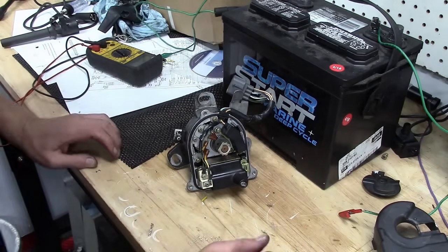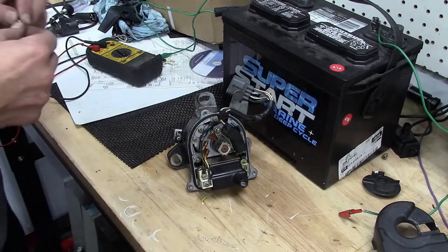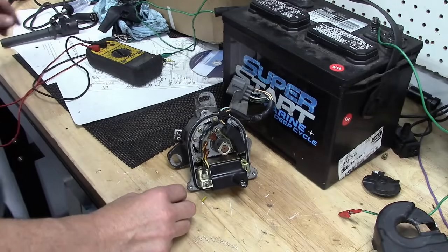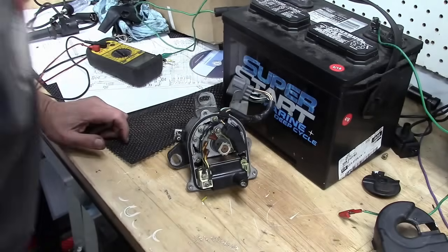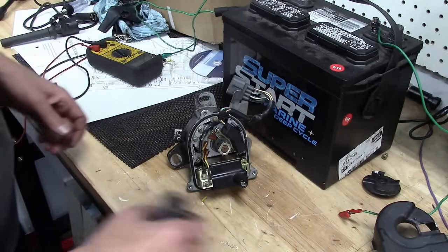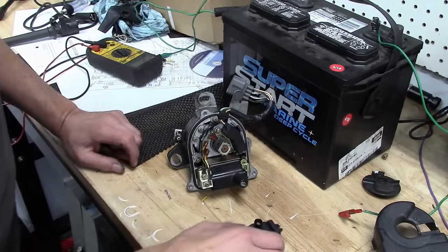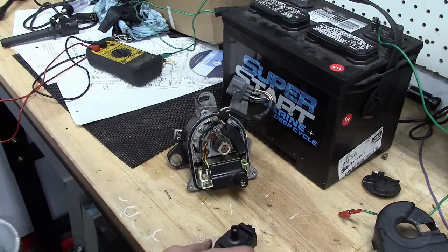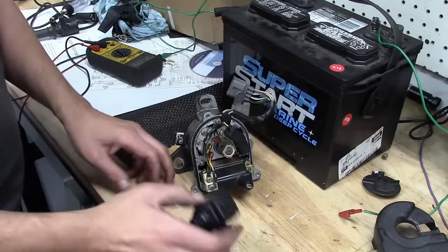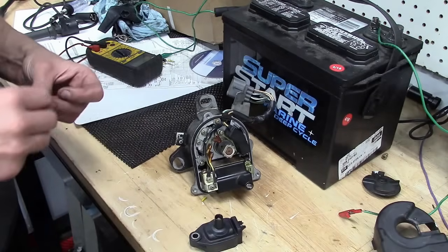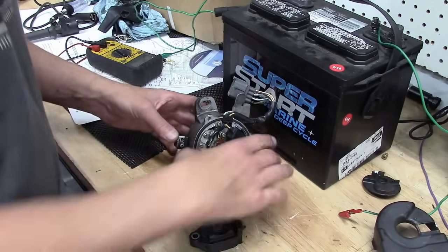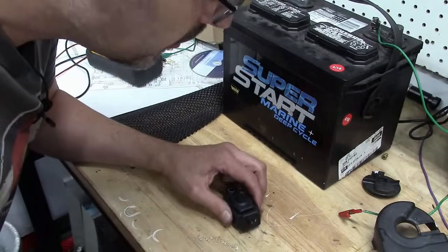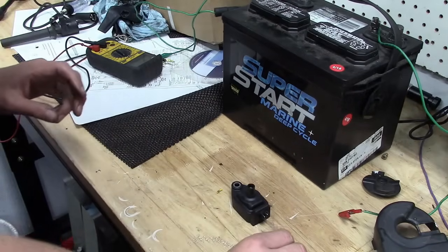Before I do that, I want to set up a positive control. I use a coil that I have somewhere around here. Let me find it. All right, well, this will actually work. I have two of them. I've got this little 2-wire coil, and then I have a 3-wire coil. I know they are good, and I use them just as controls to make sure my testing works. So we're going to set this guy aside for a second here, and what I want to do is wire this guy up to the battery.